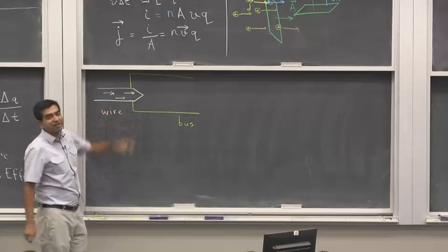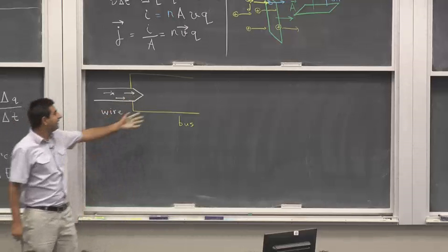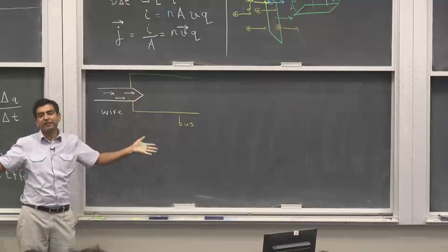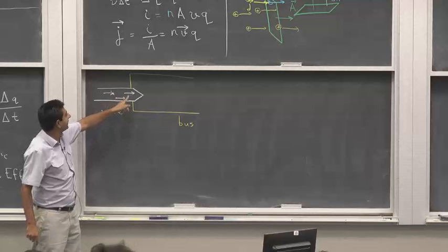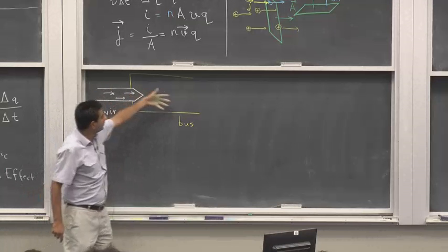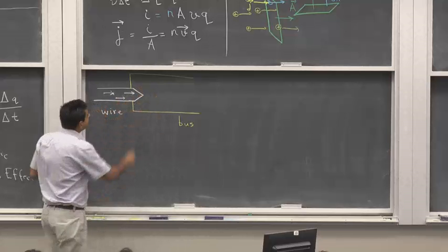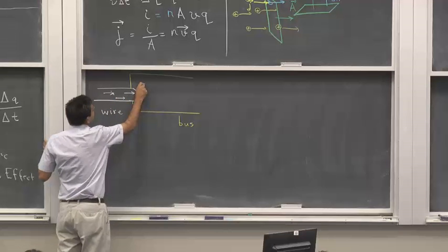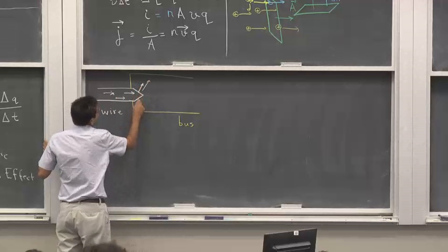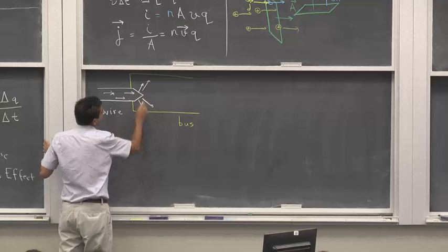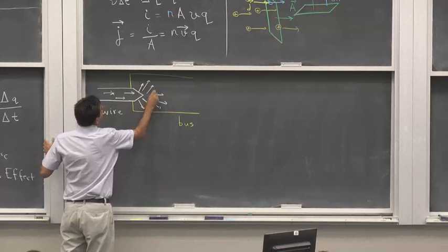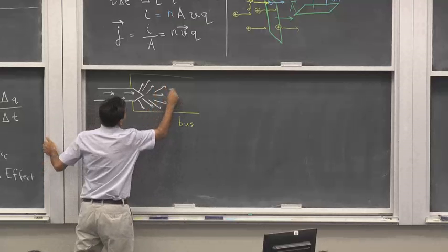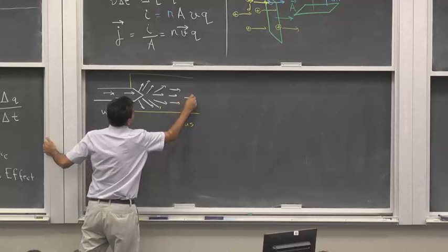but as soon as this junction with the bus arrives, these objects have different conductivities. So the current density will no longer be along the axis of this bus, it will spread out a little bit. So these are the current density vectors, and finally far away from this point conductor they are going to become parallel once again.